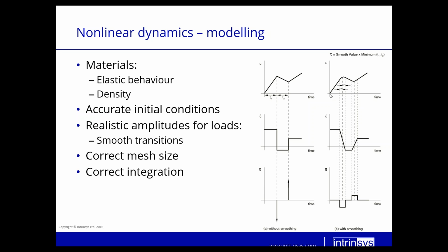You can use the smooth step amplitude in Abaqus, in which case you will still define these points, but Abaqus will automatically smooth your response. As you see, there's no more step change in your speed, but a gradual change, and thus you end up with a finite acceleration. So you wouldn't have those issues as in this case.